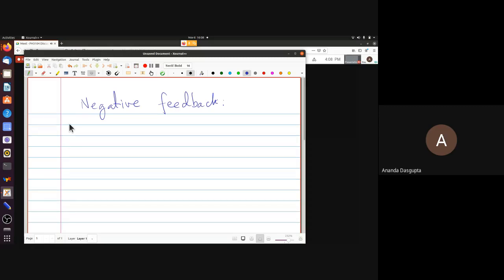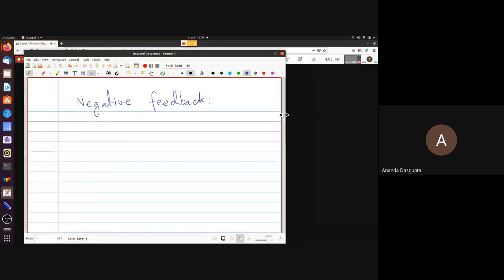And say you were listening to the radio at some frequency and you want your signal to be amplified so that you can hear a loud version of the very weak signal that's coming in. And suddenly you hear a tone which has nothing to do with your signal, maybe some constant tone at some other frequency. That would be a disaster. So circuit starting to oscillate on its own is really a bad idea. You don't really want that. So it so turned out that the culprit in almost all those cases were what is called positive feedback.